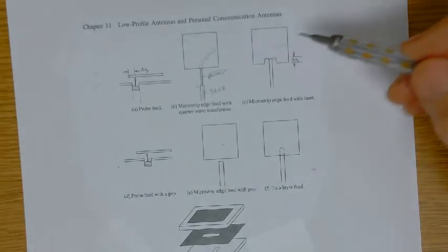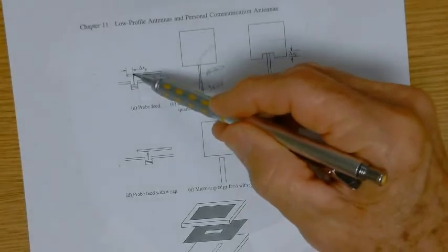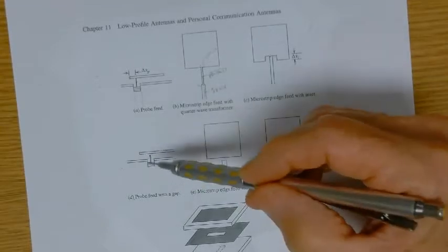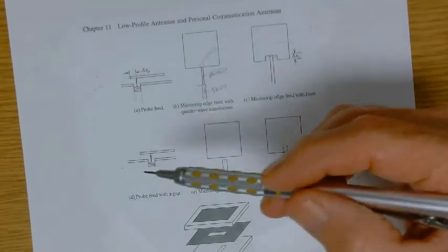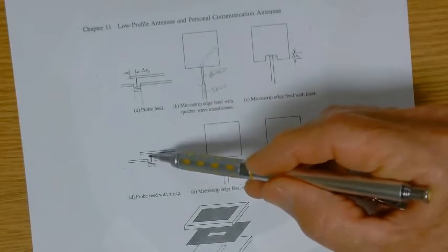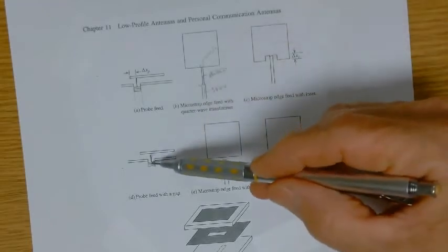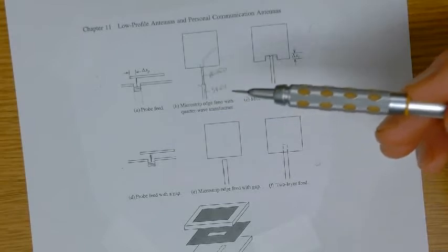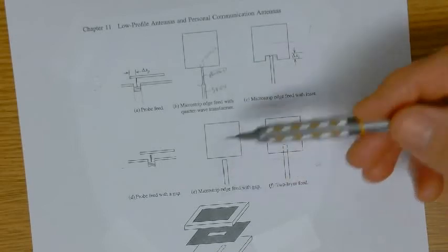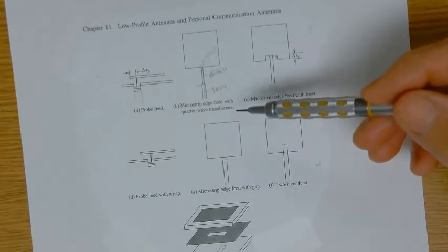Okay. So you don't even have to solder the center conductor to the patch. You can feed this with a so-called proximity feed. It doesn't actually touch, but it couples electromagnetically. You're at high frequencies now, so it's not like circuit theory. That's not an open circuit. That thing actually couples into the patch. Why? Because the dimensions of the circuit are on the order of a wavelength. We talked about that. Whenever dimensions of the circuit become on the order of a wavelength, field theory has to be used to predict performance. You can no longer use simple circuit theory.